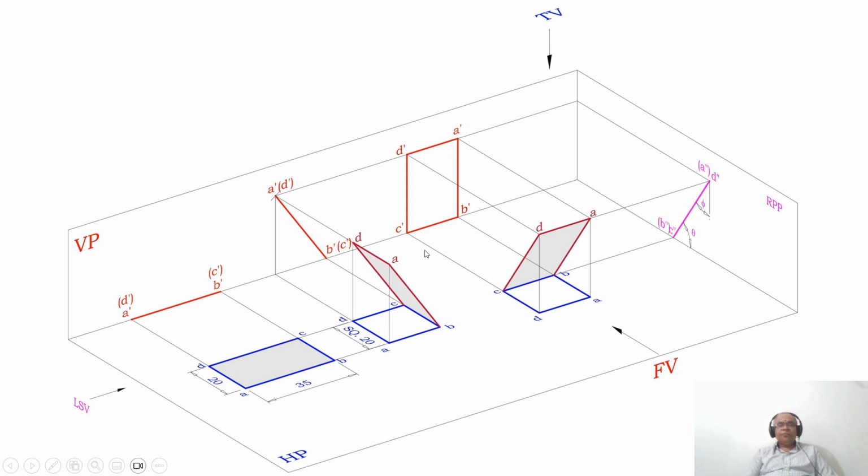So when you look from the top view, both B and C are equidistant from the vertical plane. Now the line is parallel to VP. Then what I am doing is rewriting the same sketch by rotating at an angle of 90 degrees with respect to BC. So BC is going to become parallel and AB, which was parallel, is going to become perpendicular. Then AD, which is perpendicular, will also become parallel to VP. Then CD, which is parallel to VP, will become perpendicular here.